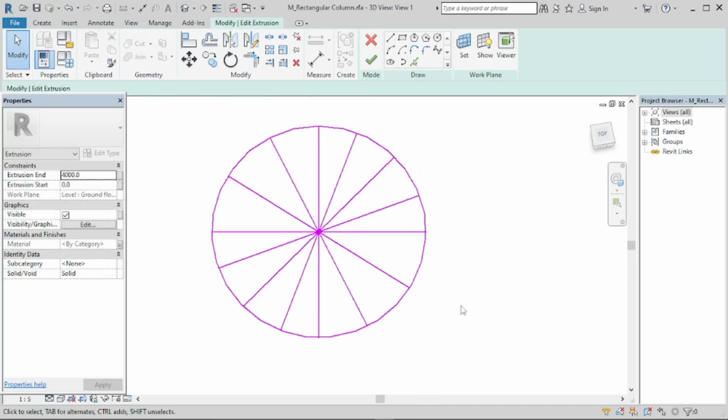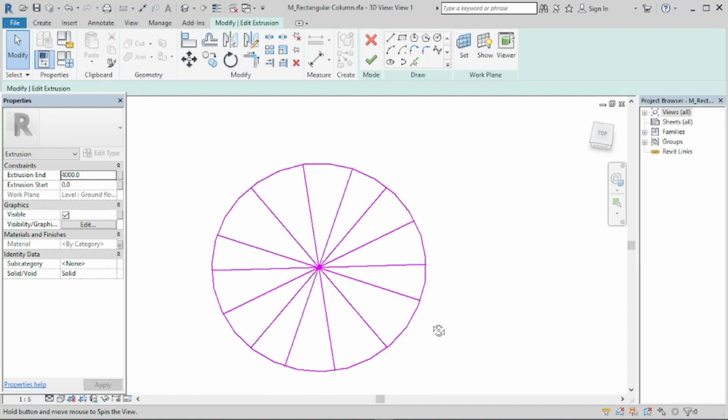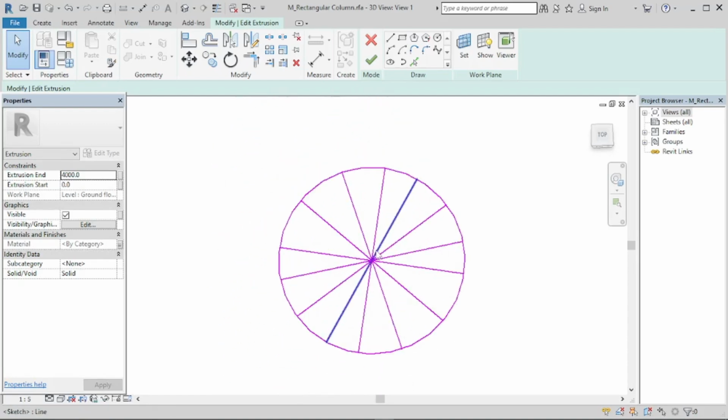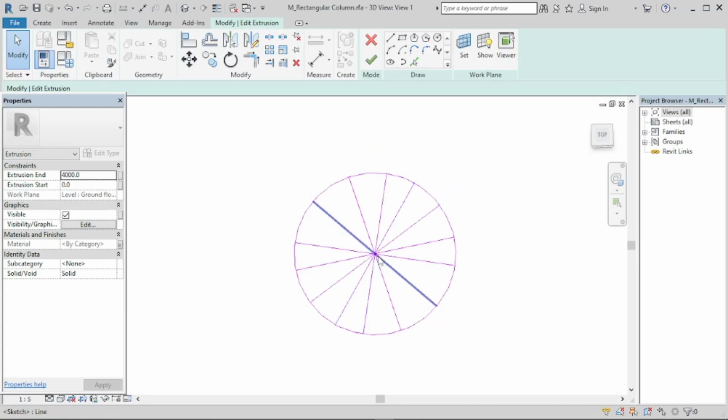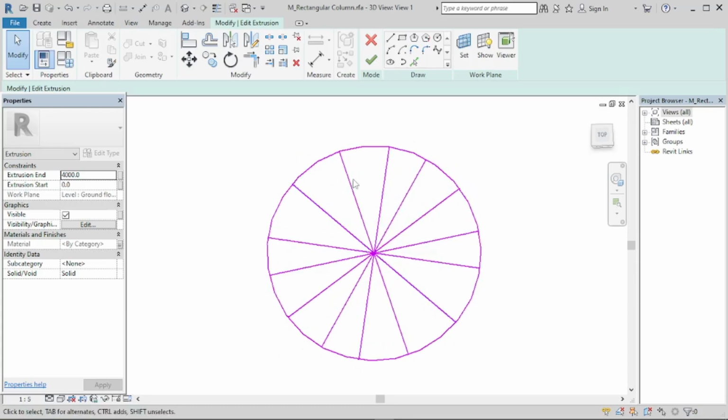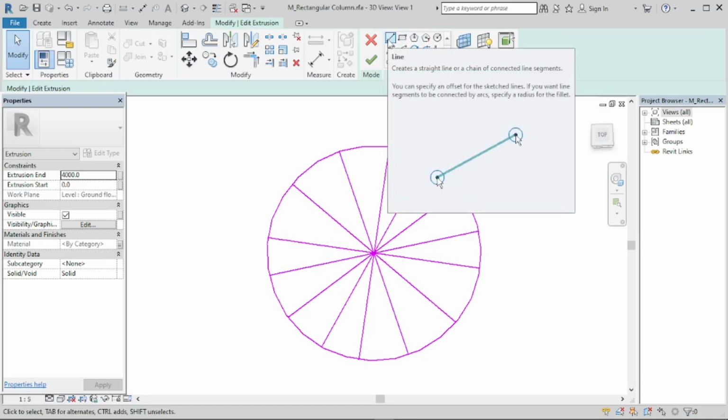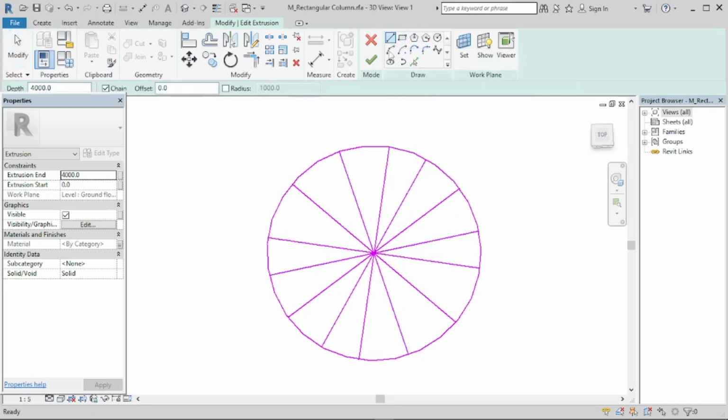So right now we've got these segments divided, so we're just gonna get the edge attachment. But personally I feel like the segments are not enough, so probably we could add more segments to make those linings on the wall of the column much thinner.